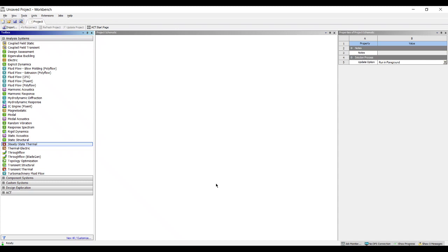Hello, welcome to the Ansys video tutorials. In this video tutorial we are going to see a two-dimensional heat conduction problem inside the Ansys Workbench. Let me first select the steady state thermal analysis system. You can see over here this is the steady state thermal analysis system. Steady state means basically it is independent of time.